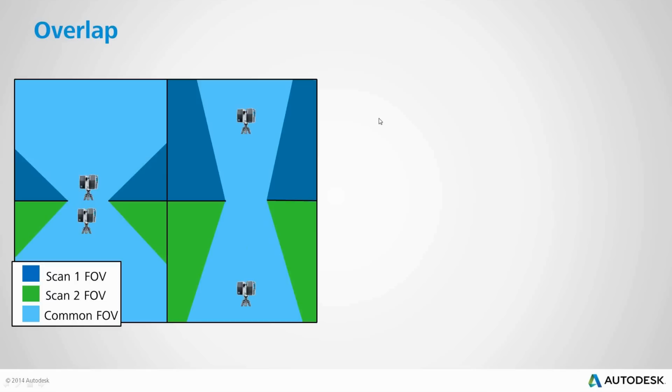So obviously this is better to scan closer to the doorway. In the example that we have here on the left, you could improve that scenario by actually adding a third scan right in that threshold there to get the right amount of overlap.